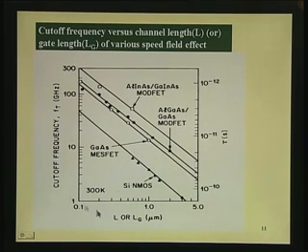achieved. These points are the actually measured cutoff frequencies with silicon MOSFET, and this is of course the estimated cutoff frequency. You can see on the x axis we have the channel length L, on the y axis we have the cutoff frequency Ft or Fc, what we are calling. So, you can see here, if I go from 0.1 micron, 1 micron, 5 micron, nobody talks of these days, except maybe in some academic institutions where they want to try out some things. Even in our laboratory we have 1 micron technology.